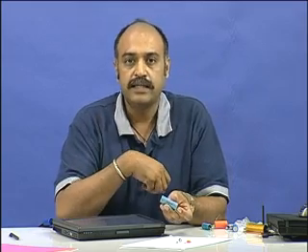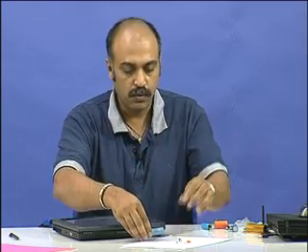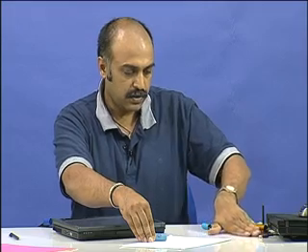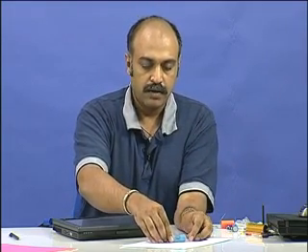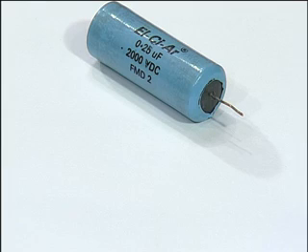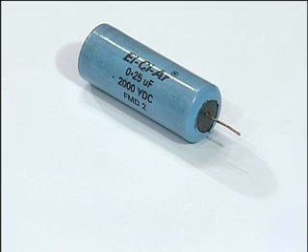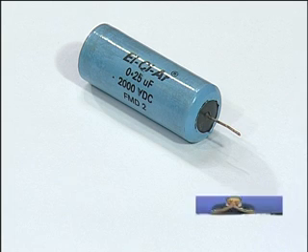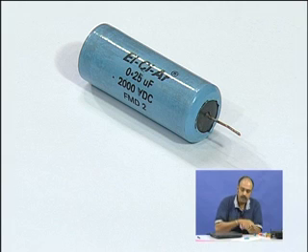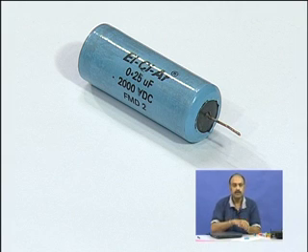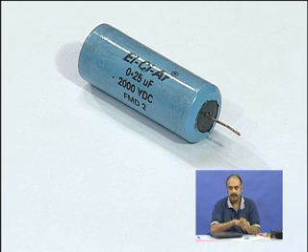So, due to that the size also will vary. As the currents in the capacitor increase, the sizes will also go up because the ESR is going to dissipate that. Now, here is another non-polarized capacitor which can handle much higher current than the ones you just saw, which means that higher current carrying capacitors should have lower equivalent series resistance or ESR. So, this is one such non-polarized capacitor normally used for snubber applications.